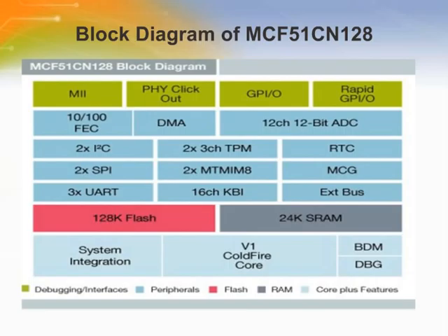It has 2 3-channel 16-bit TPM blocks, RTC, which is configurable, TCP/IP communication suite, RTCS. It has Telnet, FTP, HTTP. Other features include 2 SPI interfaces with full duplex or single-wire bidirectional double buffer transmit and receive, and 2 8-bit resolution Modulo timers with 8-bit prescaler, and up to 24 KB of static RAM, and up to 128K of flash.